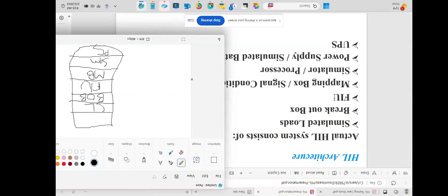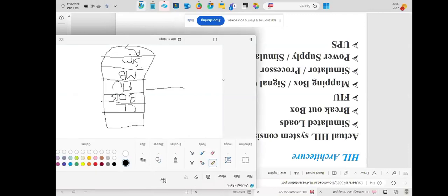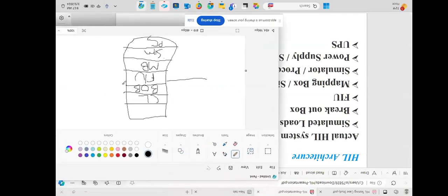Next, FIU. FIU is the failure insertion unit. What is the use of FIU? We can create failures, inserting faults in an automated way and setting them on the ECU. That could be over voltage, high voltage, short to battery, short to ground, everything.